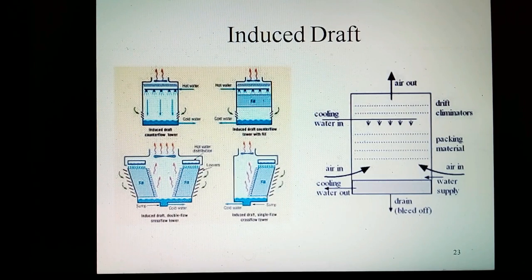Mechanical draft cooling tower. Mechanical draft towers have large fans to force or draw air through circulated water. The water falls downwards over fill surfaces, which help increase the contact time between the water and the air. This helps maximize heat transfer between the two.